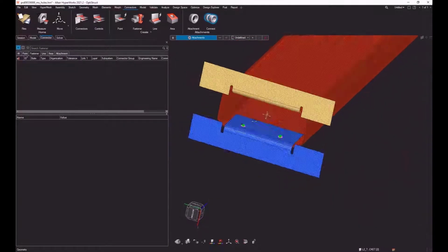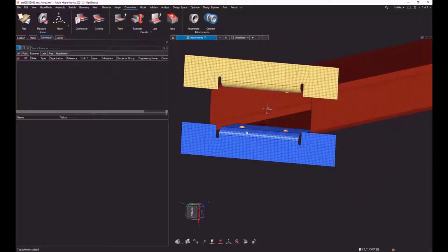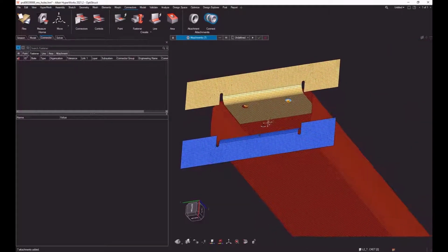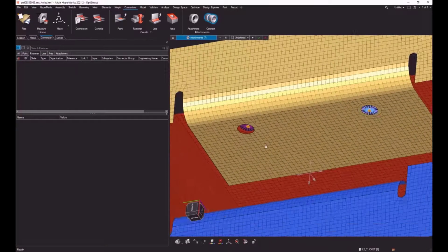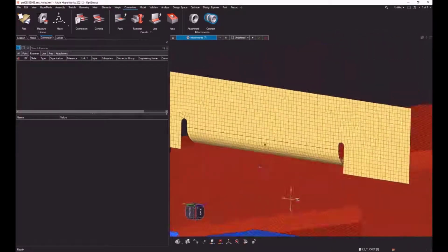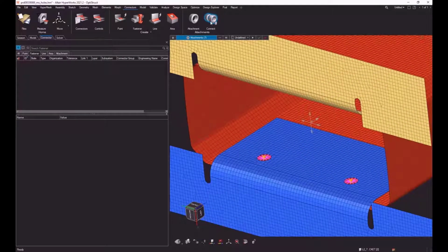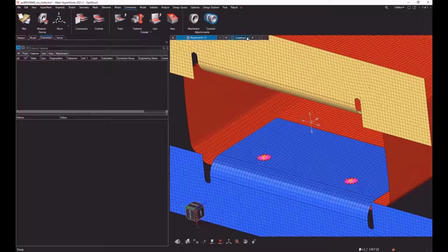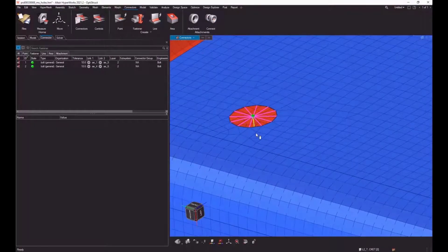What you do is you actually now grab the spiders. We'll look at why that one didn't pick that for some reason. But we'll go and grab that one and say create new. And that's going to be the connector attachment. So now we can say OK, assign it, and that's going to go ahead and create that 1D.